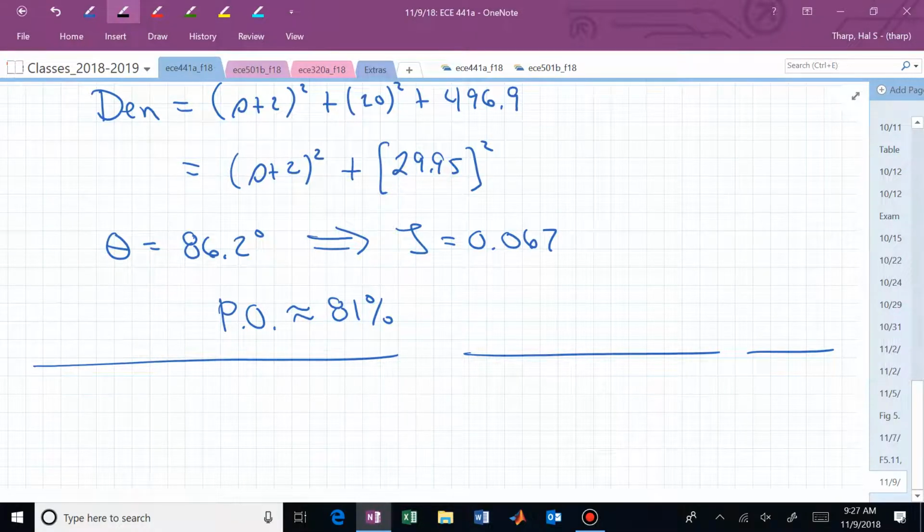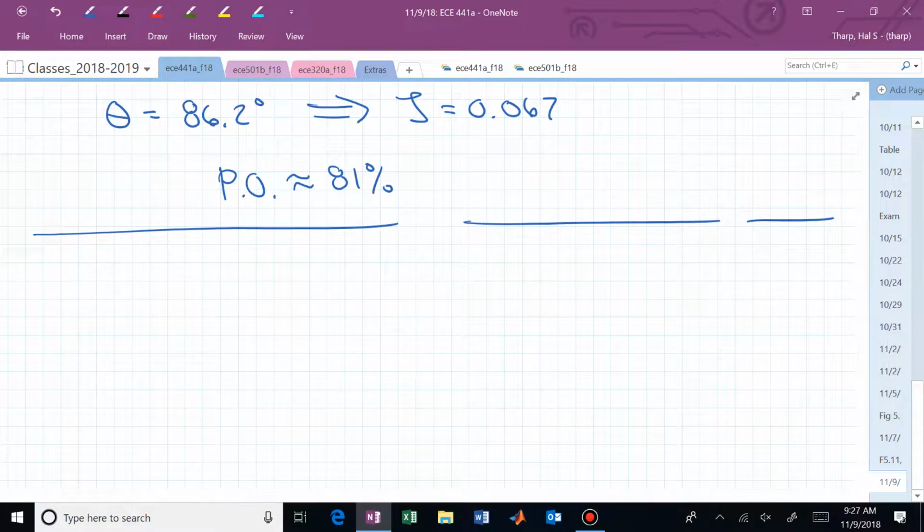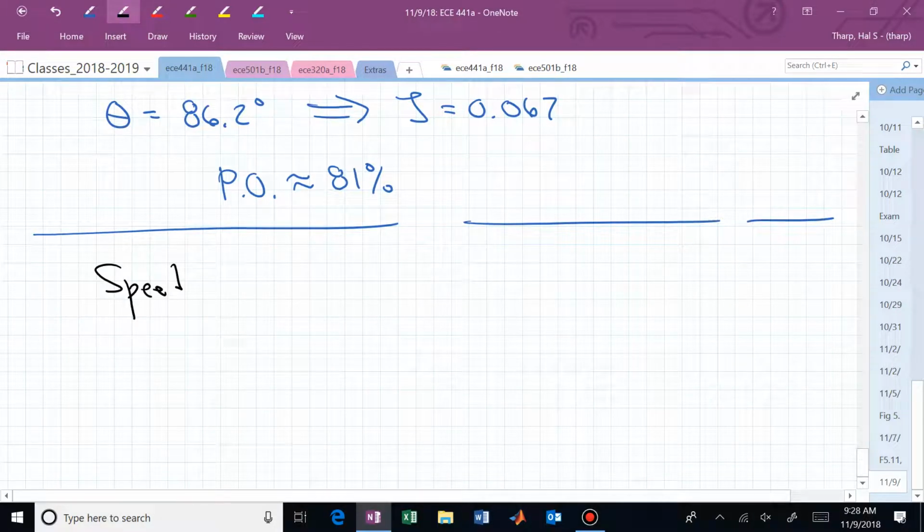Okay, you learn control, you know how to close the loop, you know how to build a controller, you build a gain controller, get a little bit more creative. Make that a little faster, reduce the settling time, shorten the settling time. And what's going to happen if we reduce the settling time? Where do we need to push those branches of the root locus? Further into the left half plane.